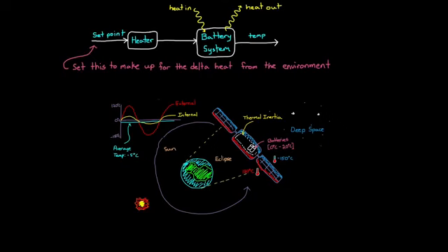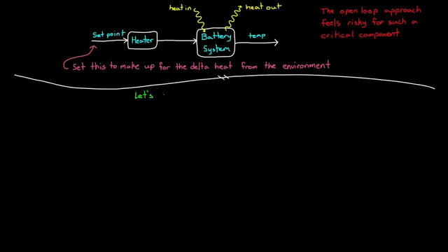We have different spacecraft components that are being turned on and off. There's eclipse as it orbits, and different spacecraft rotations to take into account. Even the sun's output changes over time. No, the open loop approach feels risky for a critical spacecraft component because I don't have confidence that we can predict the environment that well. So we should implement feedback control, at least of some type.